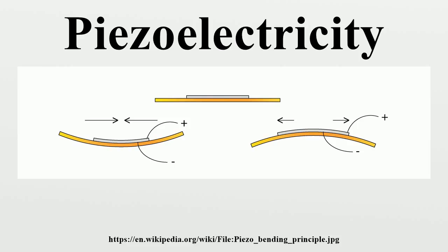Generally D and E are vectors, that is, Cartesian tensors of rank 1, and permittivity epsilon is a Cartesian tensor of rank 2. Strain and stress are, in principle, also rank 2 tensors, but conventionally, because strain and stress are all symmetric tensors, the subscripts of strain and stress can be relabeled in the following fashion: 11 to 1, 22 to 2, 33 to 3, 23 to 4, 13 to 5, 12 to 6.